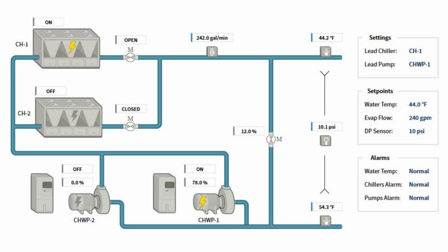Control and automation. Modern chillers are intelligent machines. Microprocessor controls continuously monitor chilled water flow, temperature and pressure, condenser water conditions, compressor discharge and suction pressures, oil levels, vibration, and refrigerant charge. Safety and diagnostics. Controllers protect against low temperature, high pressure, motor overload, and loss of flow. If water nears freezing, the controller automatically reduces compressor capacity to recover safely.